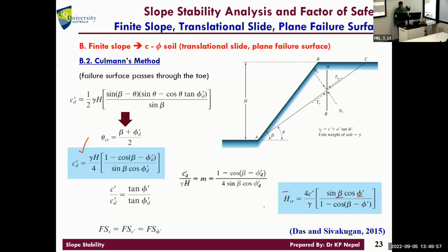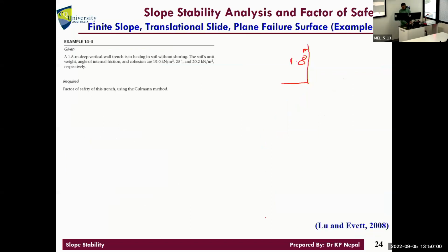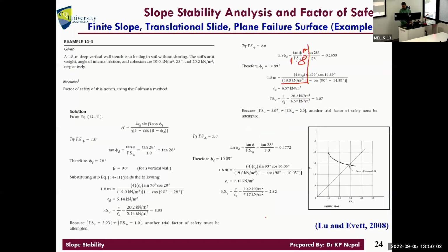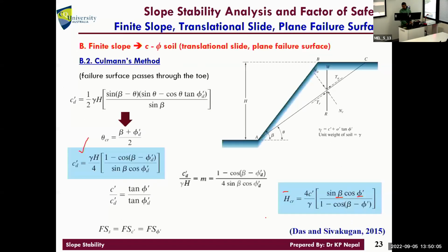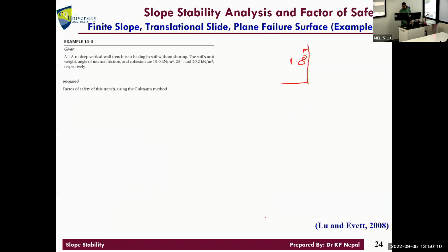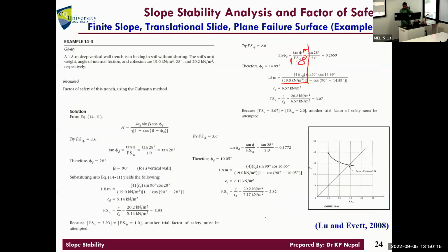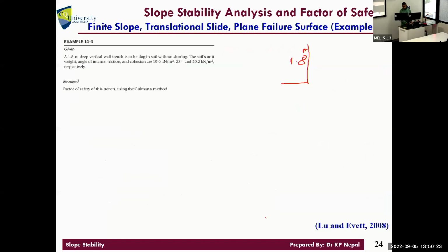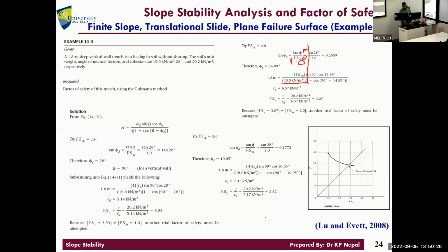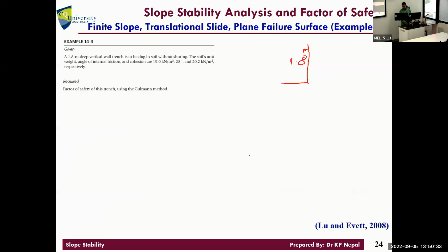CD by gamma dash. Can I have a little look at that? For CD, that's the developed. I think I didn't correctly put the equations in order. So that's one CD. So that's the critical height. Same phi dash. Same. That is the factor of safety 1, right? CD, so C developed, L1, because the critical height is 1, yeah? How much? 1.8. All right.